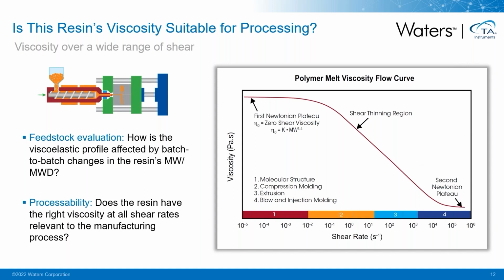In polymer processing, melt viscosity is always the key parameter to processing engineers. For example, people always ask questions such as, is the viscosity of this resin suitable for extrusion? Many of the polymer manufacturers only provide their users with a simple melt flow index value to correlate with their resin's melt flow property. This single point evaluation is proved to be not sufficient.